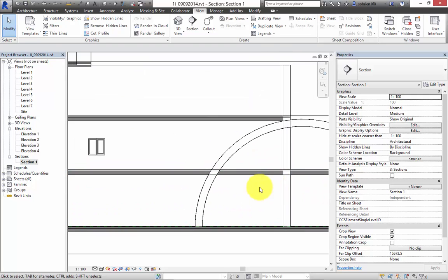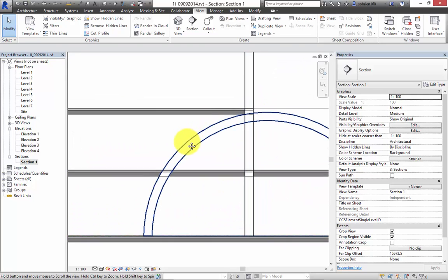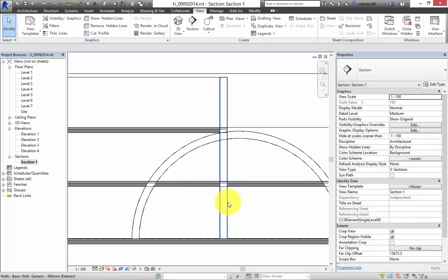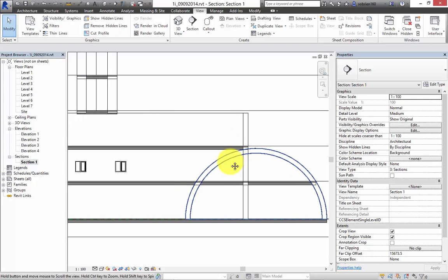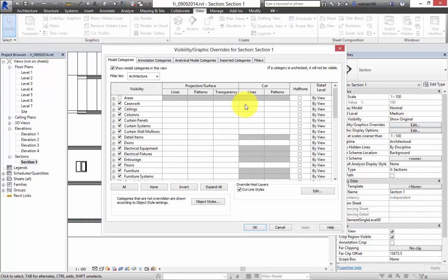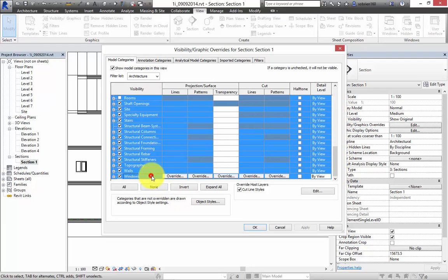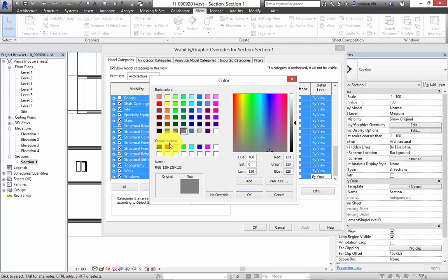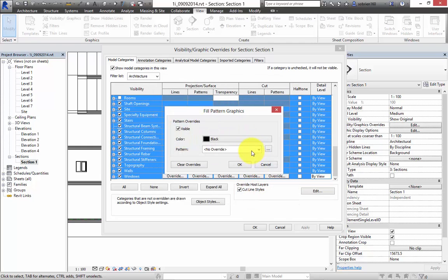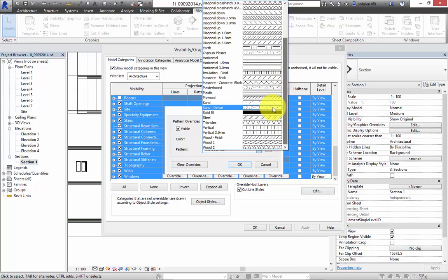Now I need to go around and clean it up a bit. For example, this dome runs through the wall, and these floors are running through the walls and so on like that. They're not cleaned up in terms of construction, but they're a perfect starting point to start to clean things up. The other thing I can do here is change the overrides of how things are displayed. And I'm going through this very quickly, but I'll go through it again and again over the next few weeks. And I can change everything so that it is black, just to make the expression of the,